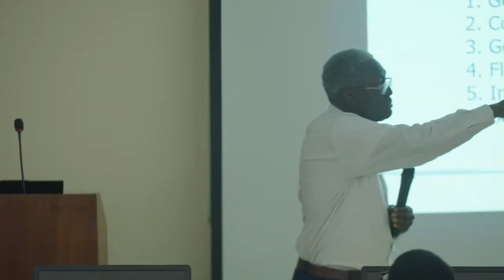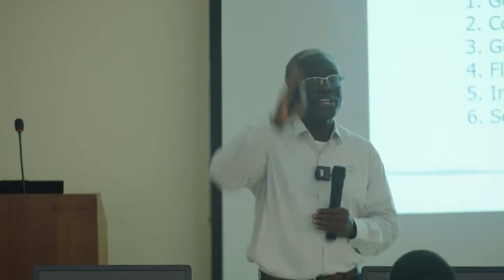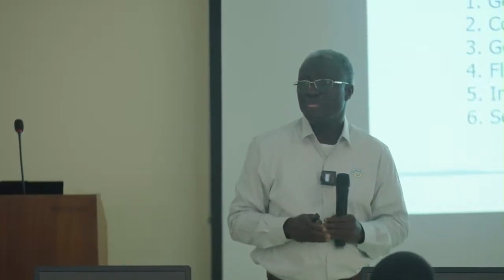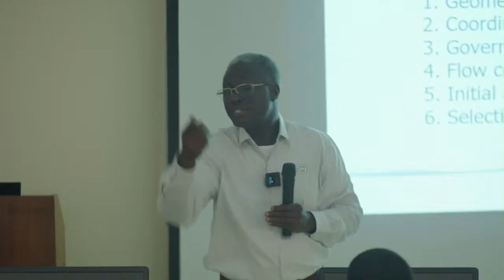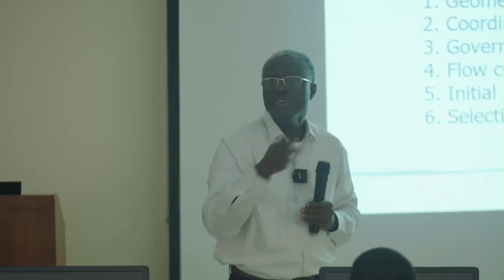If I want to do a CFD analysis of superimposing air conditioning systems in this room, we need to start out with a situation where there's no air conditioning in this room, and so the temperature is high, above 21 degrees Celsius. Now, then put in the air conditioning system, turn it on, set at, say, 17 degrees C. How does the temperature in this room vary with time?